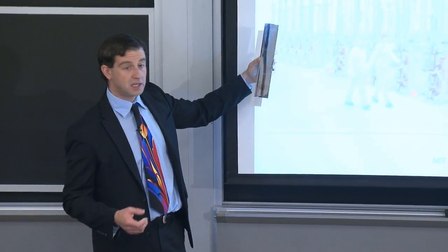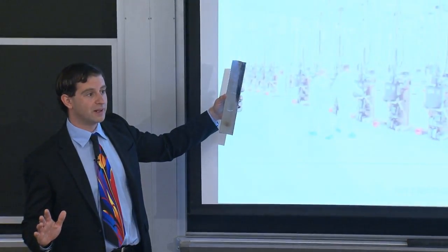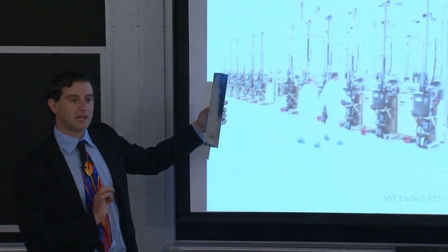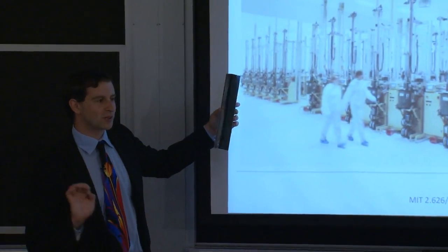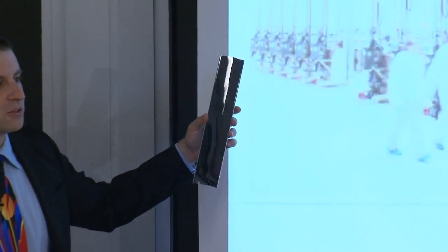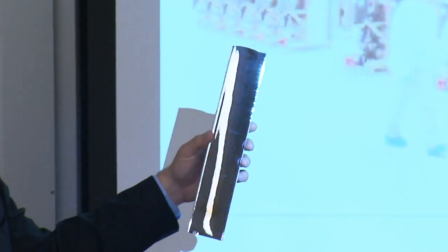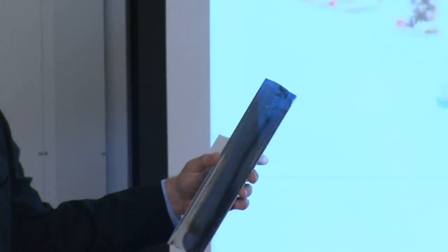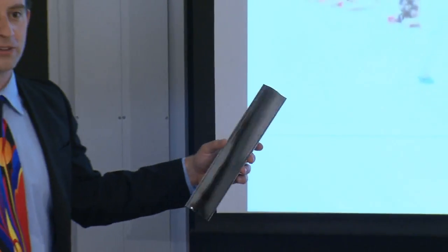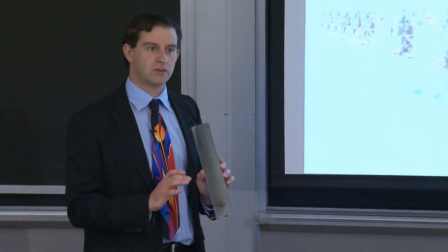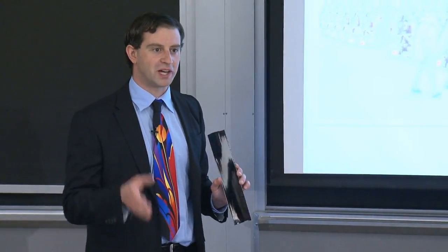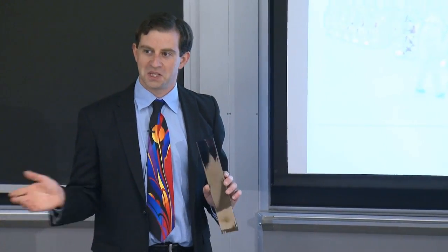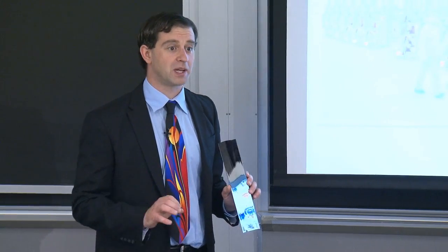And if you look very closely, it really is a single crystal. The growth method to make this, though, was extremely intricate and involved, among other things, control of the temperature of the liquid silicon to within 1/100 of a degree Celsius at melting temperature, which is an extreme feat of engineering. The uptime of these pieces of equipment, meaning the growth time, was around 50%. And the other 50% of the time, the operators were trying to make it work.